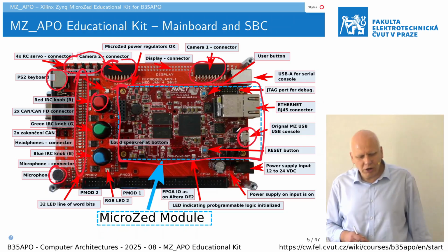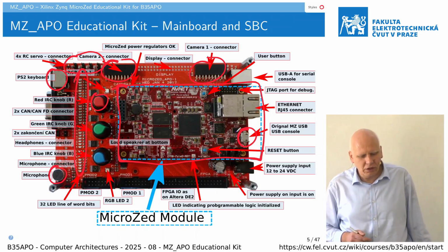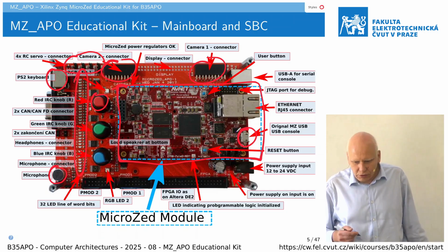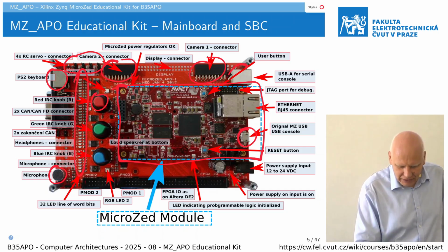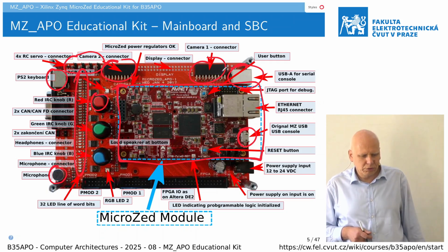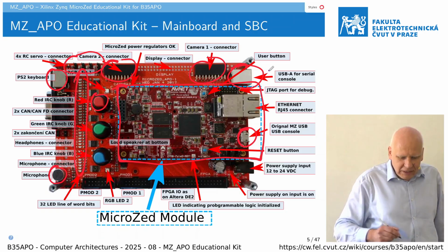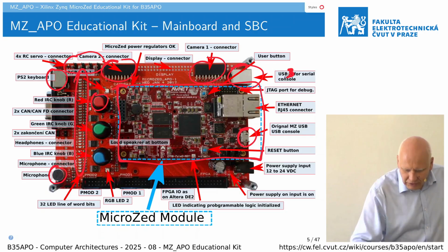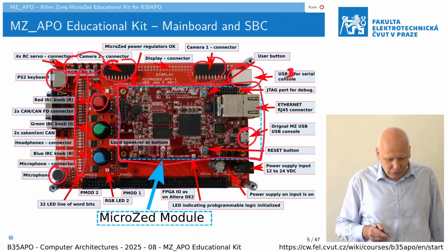The actual board has a small micro USB connector to connect the console, but to ensure that it survives for a longer time, we have decided that it is remapped by the reconfiguration through the bootloader and Linux kernel to a USB-B connector, which is more durable and survives longer.